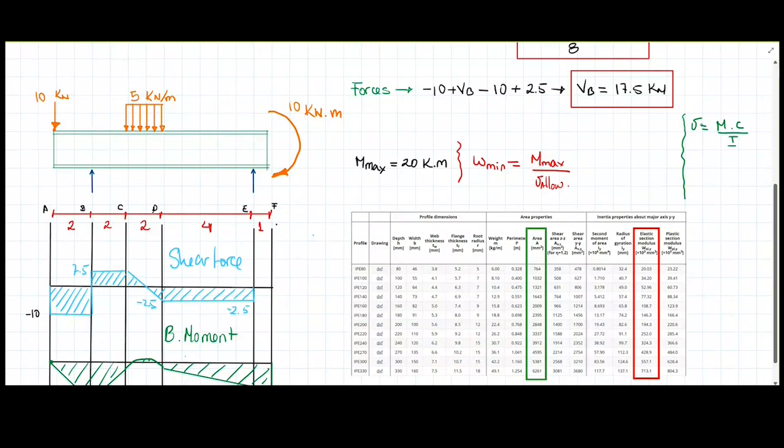Now, these two elements form W. So W, the section modulus, is simply a simplification of the formula. But it comes from the Euler-Bernoulli equation for small deformations of beams, and that's where this W is coming from. I hope that I complemented the information that I gave before.